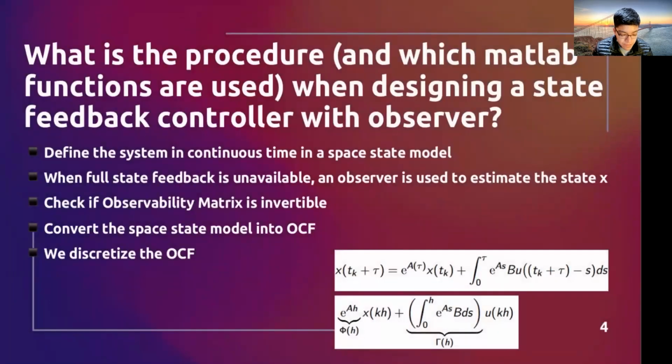What is the procedure and which MATLAB functions are used when designing a state feedback controller with observer? Well, in my own procedure, I think the most important step is to define the system in continuous time in the state space model, for example. It could also be a transfer function first.